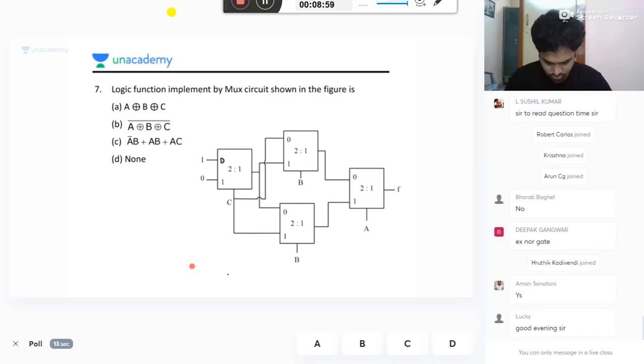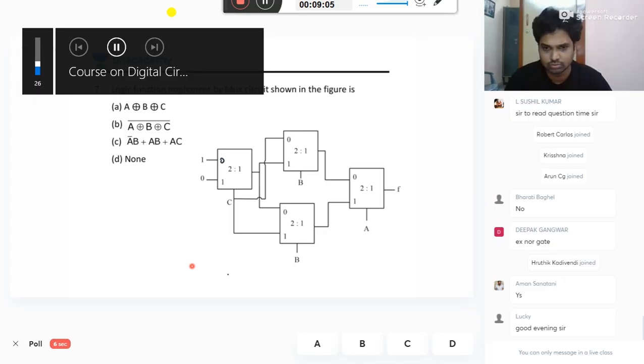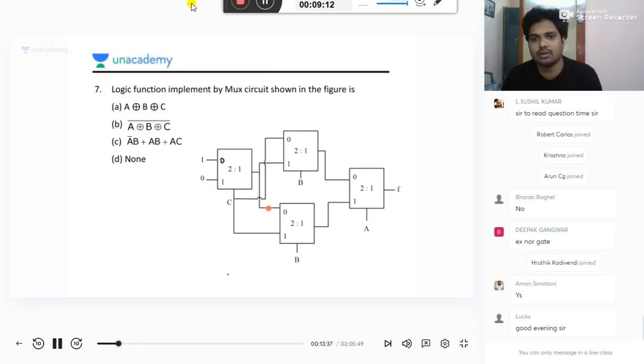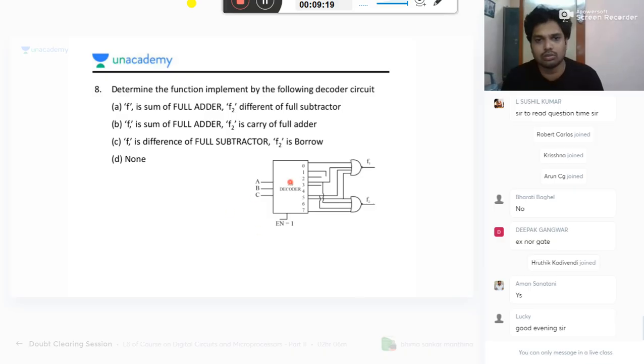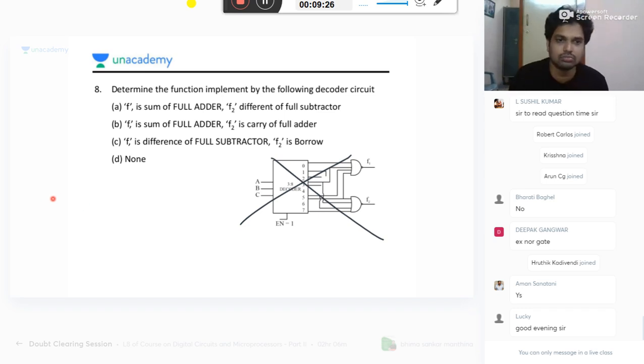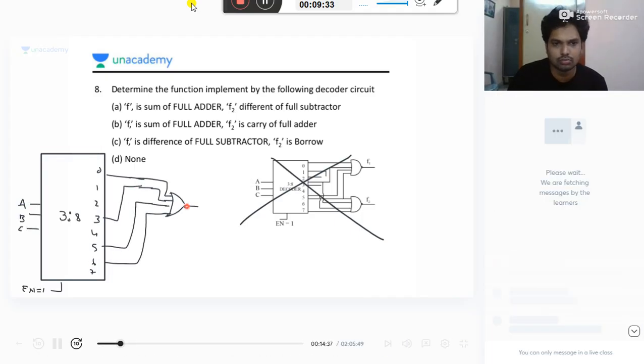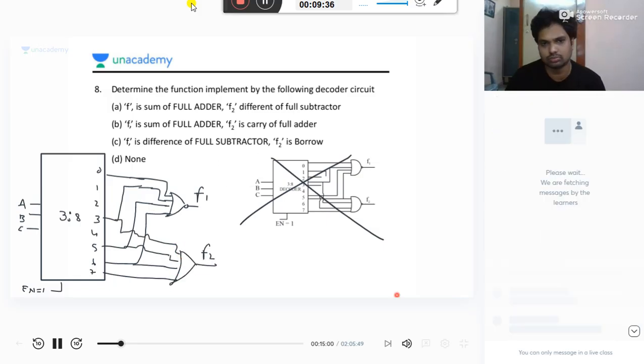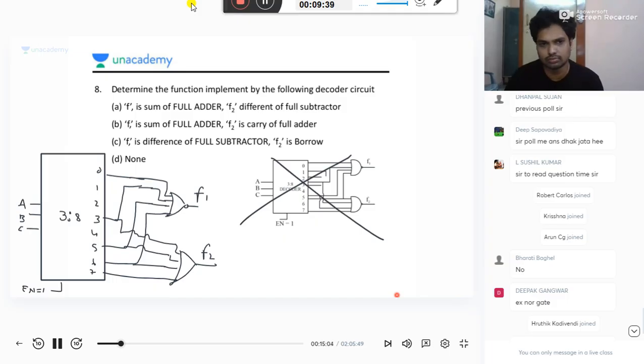The frequency of the clock applied to the first stage also has a periodicity, that is time period equal to 1 by 8 of the output signal obtained from the last stage. So from this what you can say, f is also equal to 8 times f naught, because time period is divided by 8, frequency will be multiplied by 8. Now these two you relate, both are f's, so f clock by 8 equal to 8 times f naught. Then what is f naught? F clock by 8 and 8 will give you 64. So what is the answer? Mod 64. Simple question, but tricky terminology.